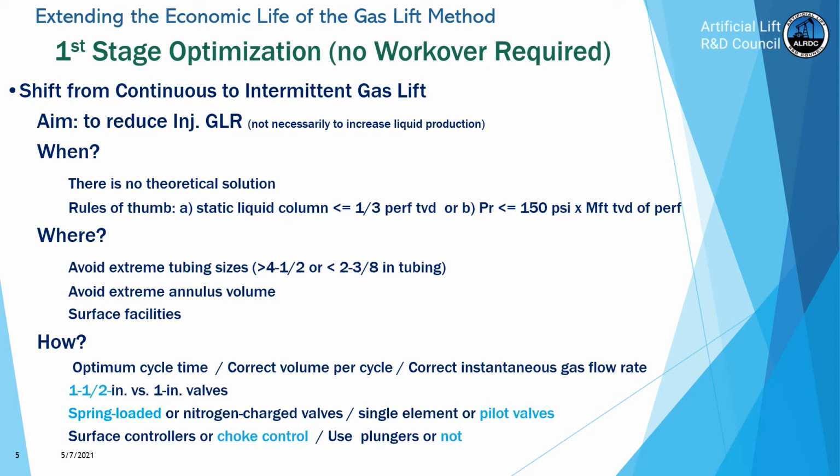That means that when the gas lift valve opens, the pressure in the annulus is going to decrease until the pilot valve closes. The gas flow rate at the surface is always very low and constant. As soon as the pilot valve closes, the annular pressure begins to increase very slowly until we reach the opening of the pilot valve again.